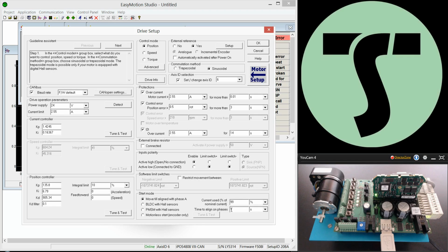In our case, this means to supply the motor in such a way that it will align itself with phase A before I start using the encoder information. Because the motor can be in any position, this alignment move can be shorter or longer. So in other words, it is not controlled in amplitude.